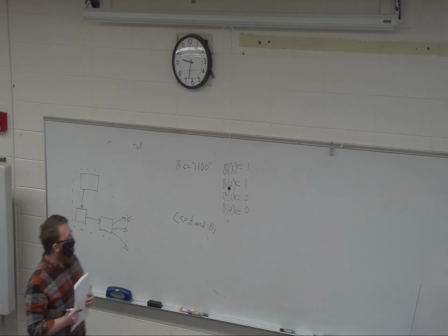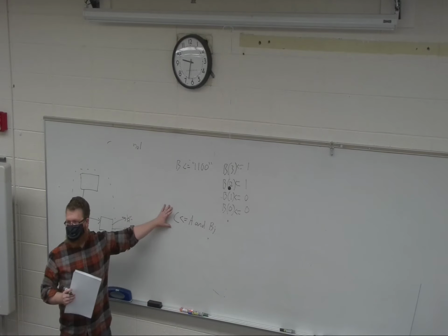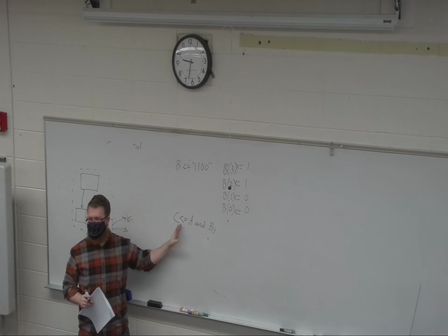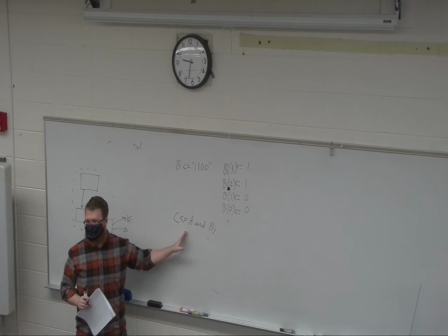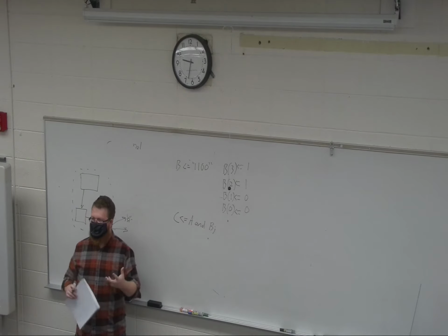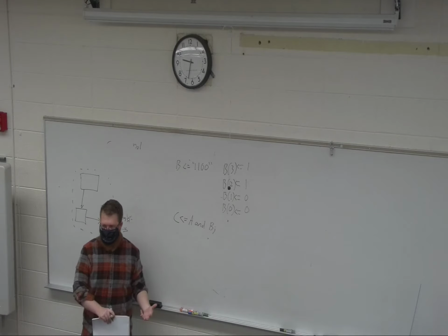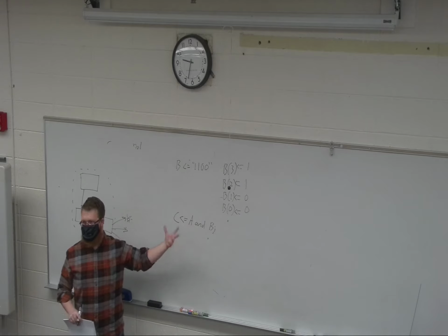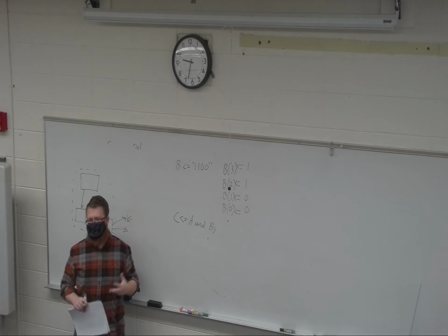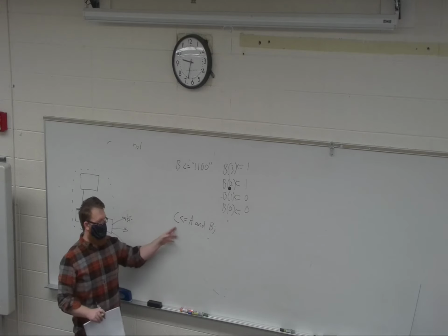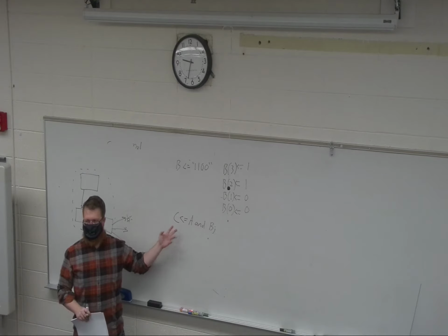You're trying to show 4 bits. Yes, so if you had previously defined C as a 4-bit, and then you tried to throw 4 bits into it, in VHDL that would cause an error because it is what we call strongly typed, meaning it will not do any automatic adjustments of the type for you. If you ever switch to Verilog, Verilog is very weakly typed, and it will try and guess what you're trying to do, and it will cram that down into 1. So you can see how VHDL is a little bit harder to program, but it's not going to let you get away with these mistakes that may surprise you down the line somewhere.